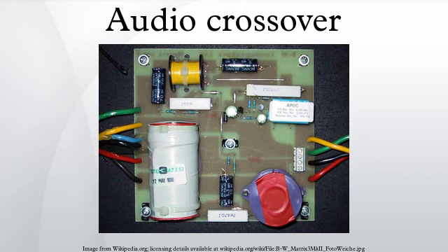A more common approach is to employ the dust cap as a high-frequency radiator. The dust cap radiates low frequencies, moving as part of the main assembly, but due to low mass and reduced damping, radiates increased energy at higher frequencies. As with whizzer cones, careful selection of material, shape and position are required to provide smooth, extended output. High-frequency dispersion is somewhat different for this approach than for whizzer cones.